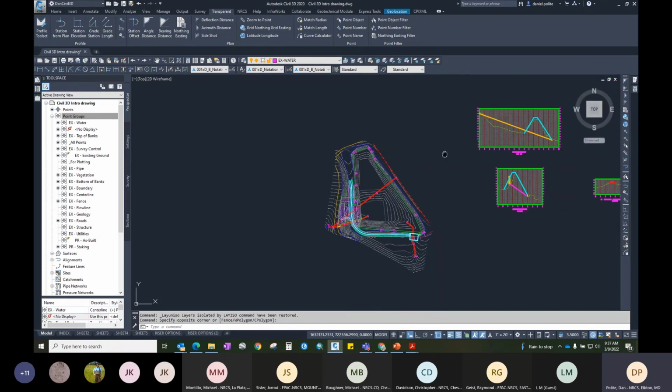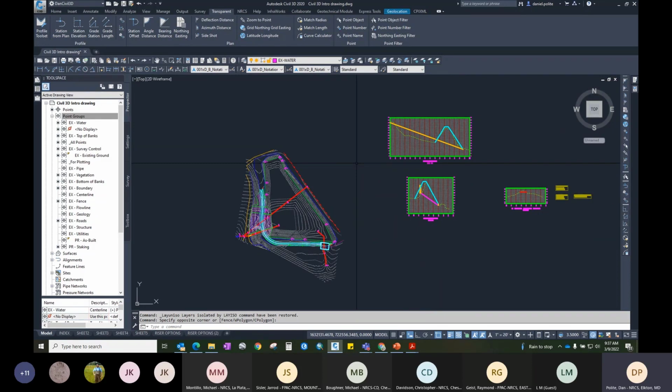Another nice function, and people that I've helped out in doing some one-on-one trainings or troubleshooting with will notice that I do some things with model space viewports. So in model space, you can split the drawing into different areas, called model space viewports, and then you can have different views. So you'll notice viewport controls, and then you'll have top, and then 2D. There's this in-canvas menu is what they call it. So if I hit this minus button